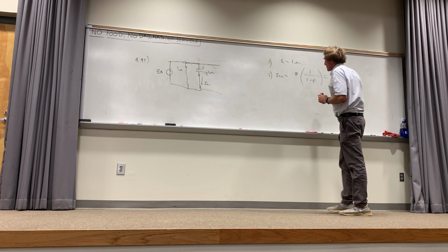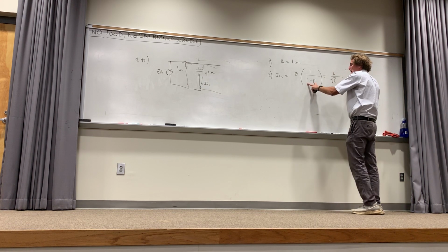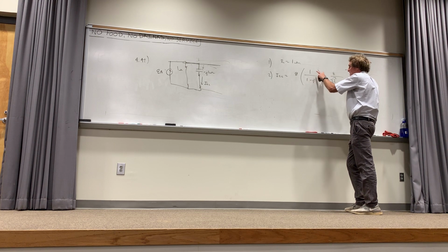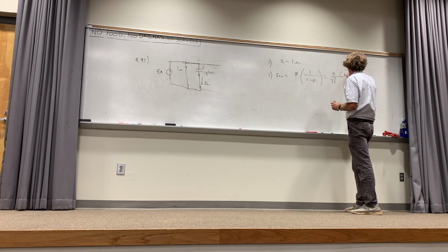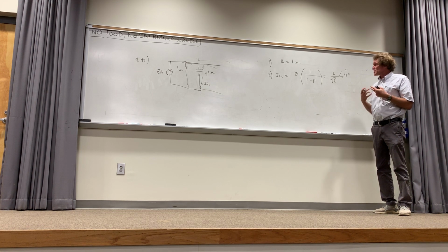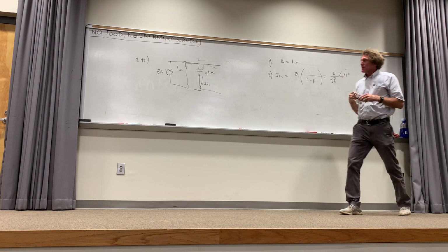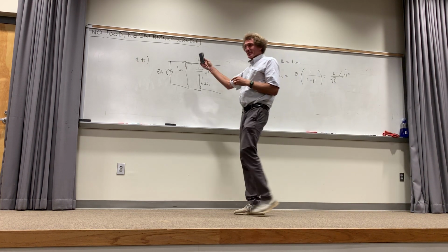That's gonna give me a current, right? That's gonna be 8, divided by the square root of 2 in magnitude. That angle's minus 45 degrees. Upstairs, it's gonna be at an angle of plus 45 degrees right here. With me? That's just the magnitude and angle of the short circuit current. Everybody got that?